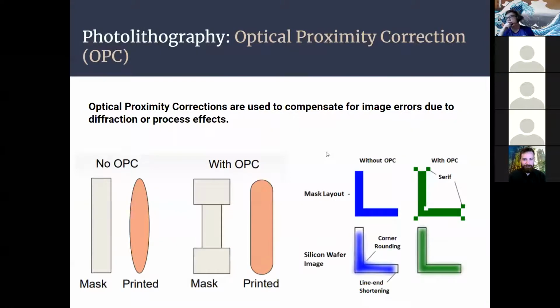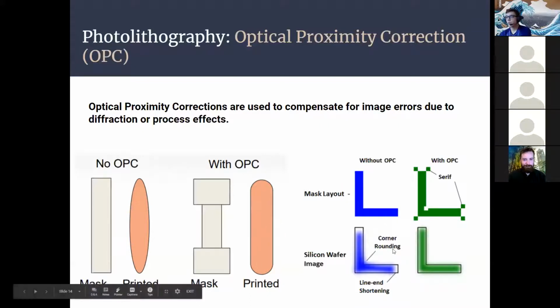And then there's also optical proximity correction, which is essentially just trying to account for diffusion of the light through these sections. It's meant to make the areas of the mask that are exposed more uniform throughout the shape. So we have these little squares on the edges to make sure that it fills out the entire image that we want and accounts for diffraction.